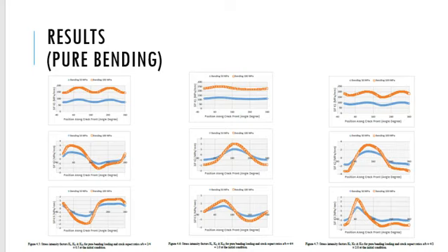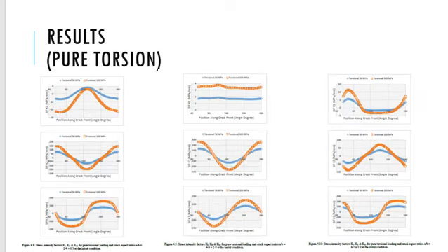For the K3 case, the maximum value is at 90 degrees for crack ratio 0.5, 90 degrees for crack ratio 1.0, and 60 degrees for crack ratio 2.0. For the K2 case, the maximum value is at 60 degrees for crack ratio 0.5, 80 degrees for crack ratio 1.0, and 90 degrees for crack ratio 2.0. For all cases, the larger value of K1 is found along the position along the crack front.